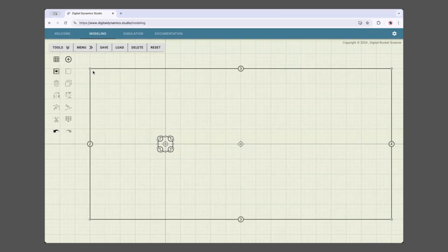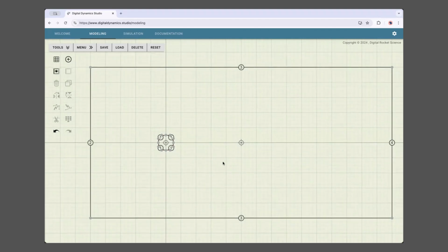Airflow, or wind flow, fluid flow, is going to be coming through boundary number 2 on the left, go around the cylinder, which is boundary number 1 here, and leave the domain on the right in boundary number 4. And the tops and the bottoms, boundary 3, are there to allow the fluid to slip along those boundaries, but not to penetrate those boundaries.